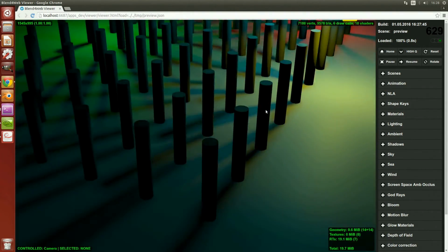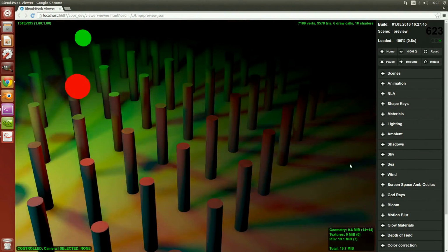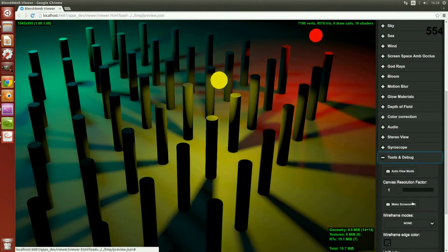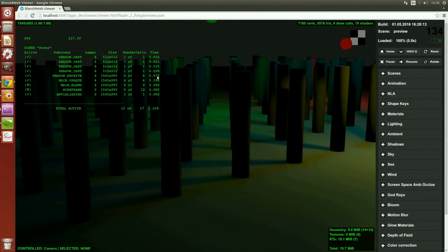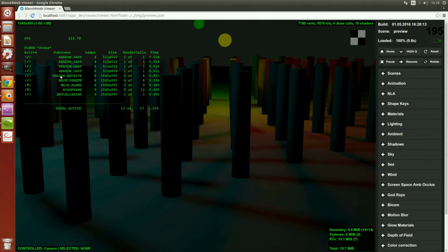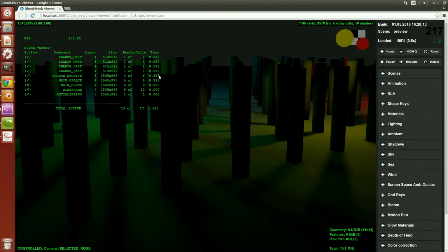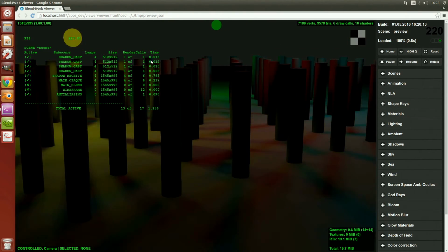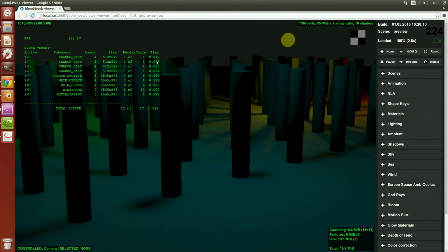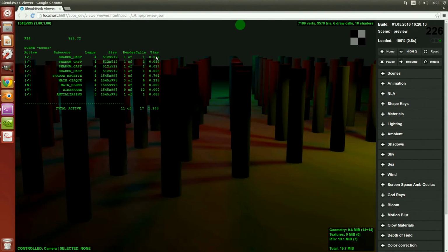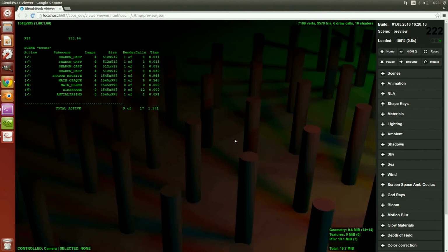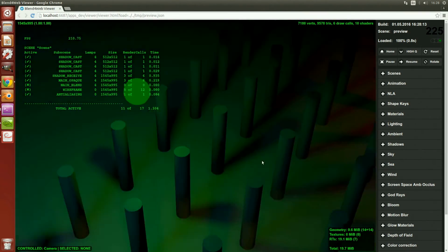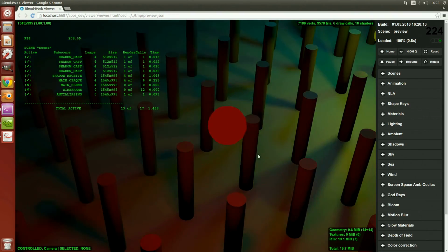We reduced the resolution of shadows, and now in the HUD we can find out that the time spent on shadow receive is less, and shadow casts cause almost no impact on the performance. So we optimized our scene really well. If you like blurry shadows, this can be combined in order to get a better optimization.